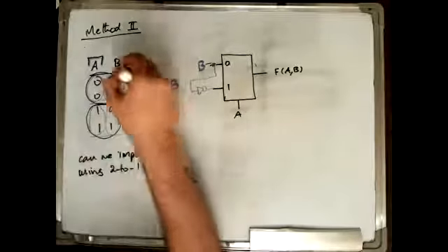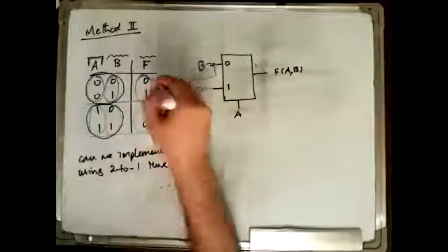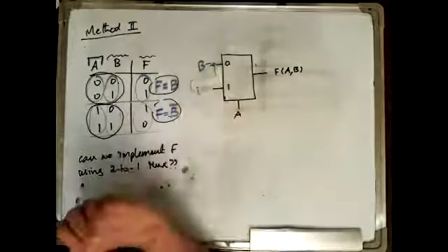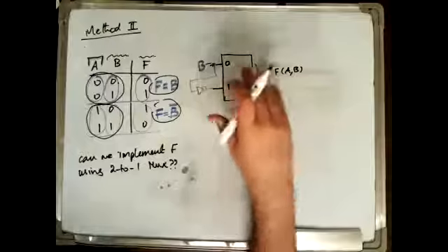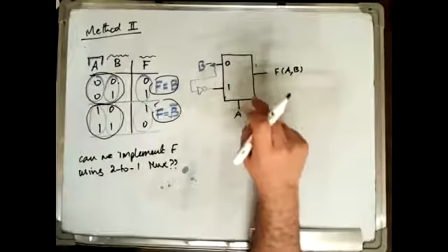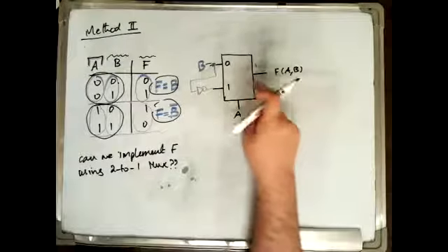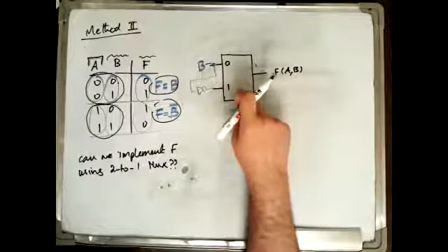And what is next? Basically, we use the remaining variables to express the function in each section, as we did here. Then we connect them as we saw here. Now, if we look carefully, we were able to reduce the size of the multiplexer from 4 to 1 to 2 to 1. And this is very effective because, if you go back to what we discussed at the beginning, what is inside this mux?